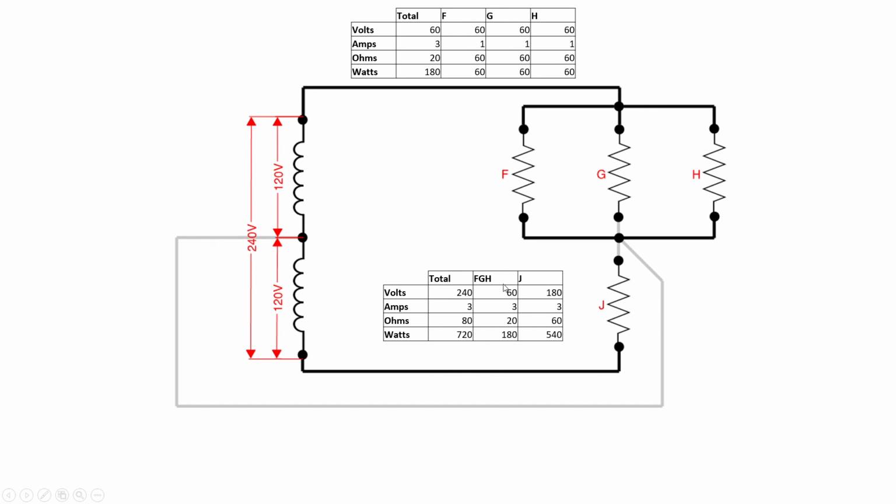My advice is, A, simplify circuits. Go back and look like we did here. Where can we isolate simple circuits and get it back to parallel and series? You have to start by finding all the resistances you can and simplifying until you have it down to one simple circuit, one parallel or one series circuit. And then you almost have to expand it back out again when you find the other values.